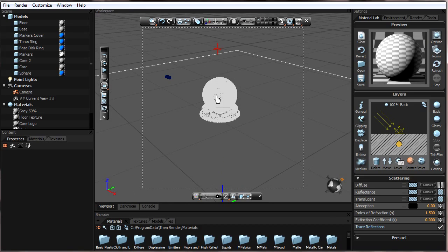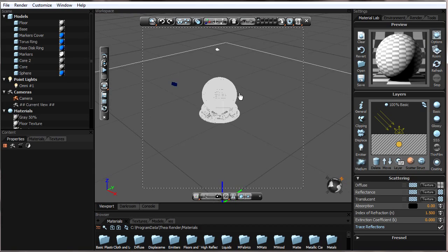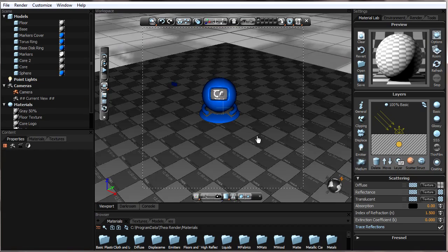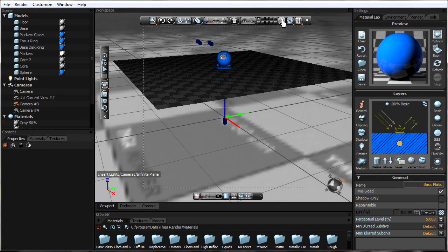So now I can use that cursor to place an object exactly where it is. I can go here, say Insert OmniLight, and it will be inserted exactly where that cursor frame was. Let's delete the OmniLight, switch back to solid mode, and I'm going to switch this back to @viewer frame.